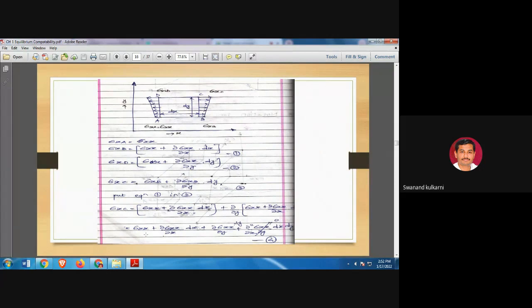So now here we are going to simplify it. When we simplify, what will we get? See here, sigma xx plus dou sigma xx upon dou x dx. Now here it will come dou sigma xx upon dou y into dy, and this one has a dou 2 sigma xx upon dou x dou y dx dy.